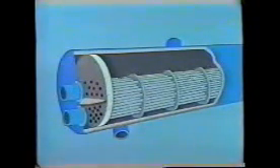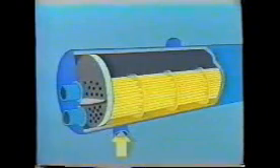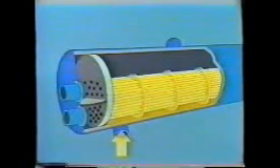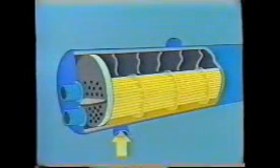Liquid refrigerant flows in the shell around the tubes. As the refrigerant absorbs heat from the water being cooled, it boils and vaporizes. The boiling occurs at a low temperature because the refrigerant is at low pressure. As the refrigerant boils, additional liquid enters the evaporator to ensure that all tubes are covered with liquid refrigerant. The refrigerant vapor rises to fill the space above the tubes. It leaves the evaporator at the top and moves on to the compressor.